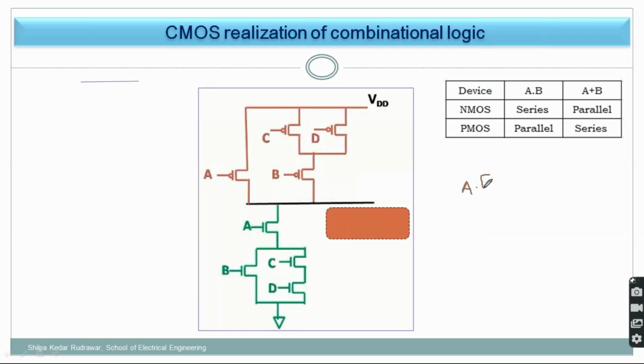So I'm just taking one bracket to avoid the complication, because this whole structure is in series with this. So what you are having is B. B is normally in series, but in parallel to B, what is there? This structure. So parallel to B, we are having a structure. So I am writing plus. For NMOS, parallel means plus. Now what you are having? Series combination of C and D. So series means into. Sorry, and my bracket is complete, and the complement logic it implements. So this is the bar.